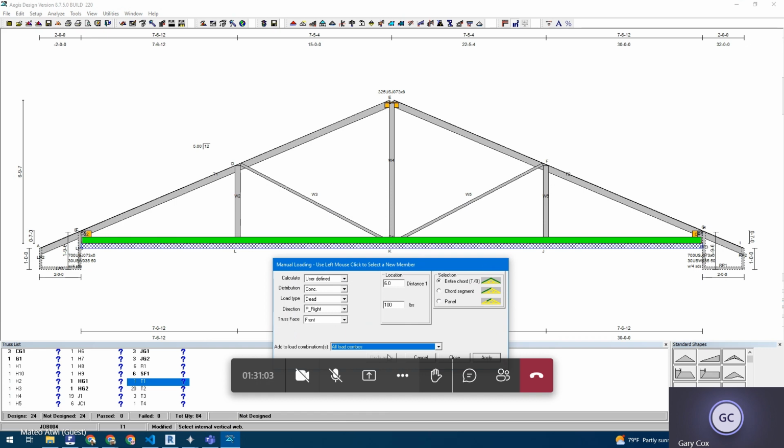There we go. You mentioned solar panel. Yeah, that's what I was trying to mimic right here. You have to go in and say it's a, well, right now you got it as a point load. So to do point load, you have to calculate how many points this is going to touch someplace, and then how much does this weigh? Say it weighs 50 pounds, just for example.